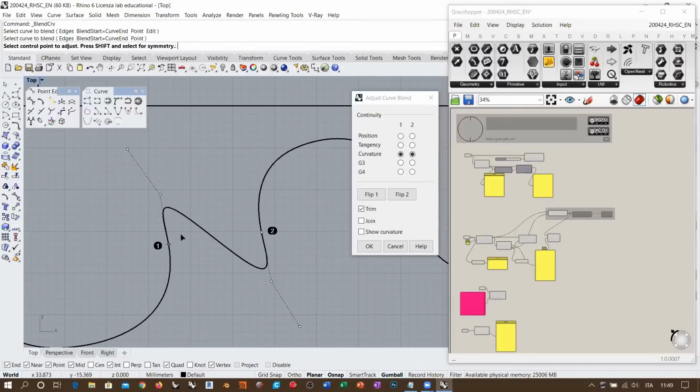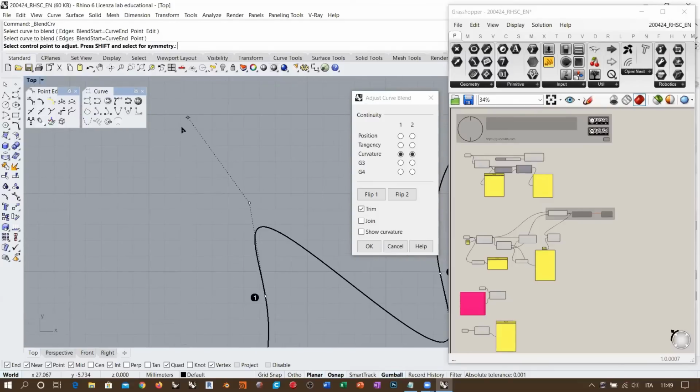And these 3 control points, if you have some imagination, you can see that if you imagine a line, a NURBS curve that starts from here, ends up here, and has these intermediate control points, the result will be an arc. These 3 control points are basically symmetrical with respect to the center control point, okay?